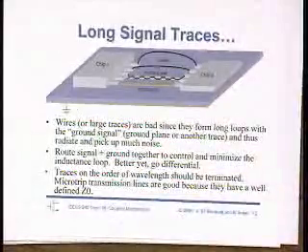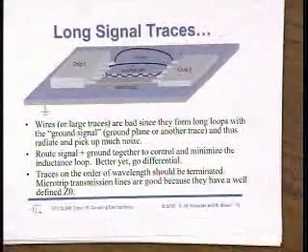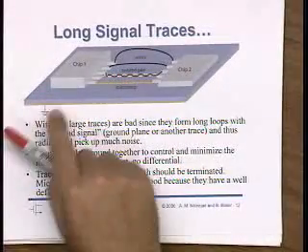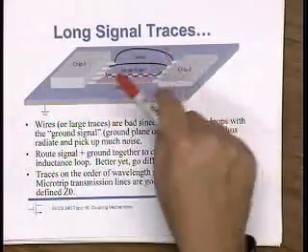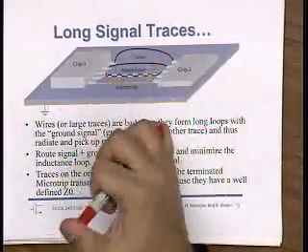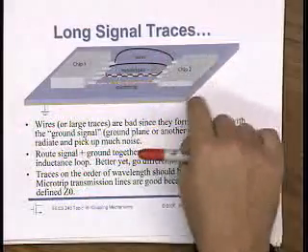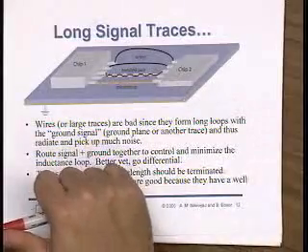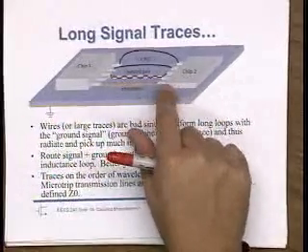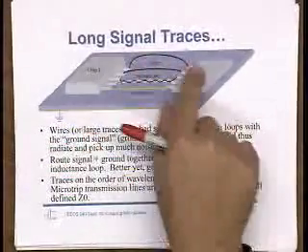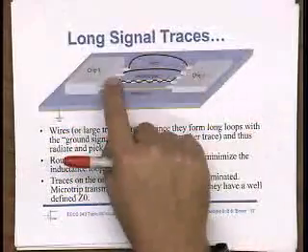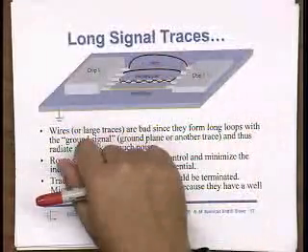Okay, how about signaling? We talk about packages, but a lot of times we have to have chips talking to each other. And moreover, even on chip, distances are getting large enough, because the frequencies are getting high enough, that sometimes we have to worry about intra-chip communication. So here we have several different options. Of course, if you're in the lab, it might just be convenient to hook a wire like this, if you're doing some prototyping. But clearly a wire is not really a good solution because it has lots of inductance, just like we talked about before.